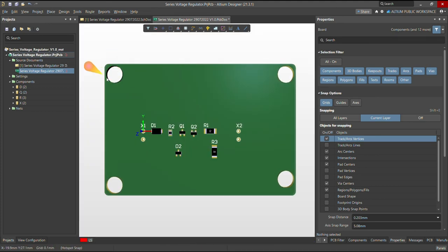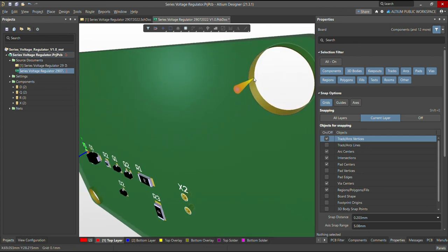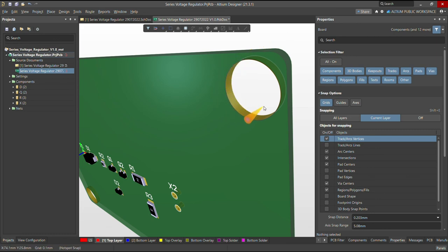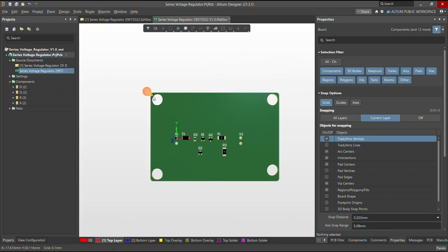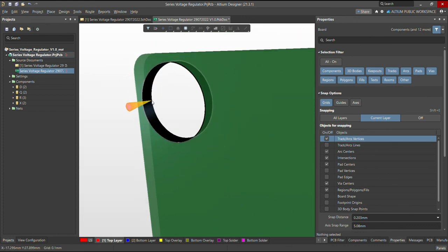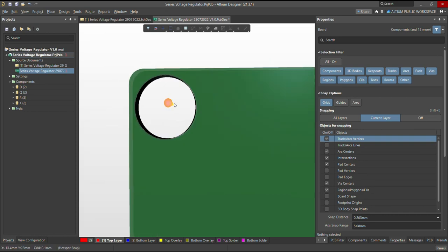For example, if any kind of screw is going through these holes, and the copper available in these holes is connected with your ground, then if you are fixing with a metal screw, and the copper inside is connected with the ground, it will definitely make a short circuit. To avoid that, you have to just disable this plated copper layer for all the holes. Here you can see that when they are plated, it looks like that, and when they are non-plated, you can see that there is no golden or copper layer.